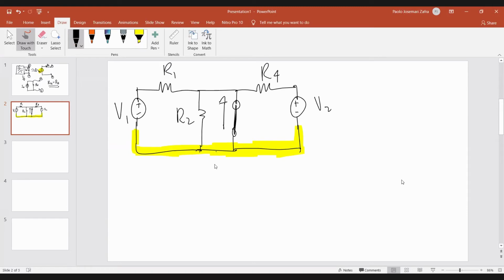So if we were to apply nodal analysis, again, you apply some ground node. This is your 0 volt. And then you solve for your IN, or your short circuit current. Do take note that when you apply the ground here, everything else, all of these points highlighted in yellow, is at zero potential. So when you're doing your KCL analysis, you can do it over this node, okay?